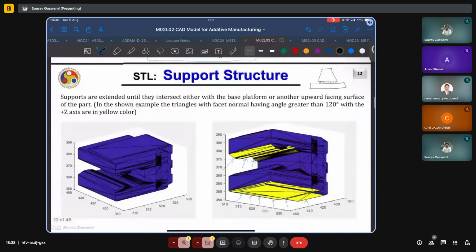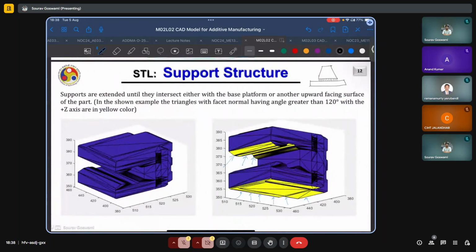In other processes such as DED, typically we may not use support structures at the bottom, and the understanding is that we'll separate it directly from the substrate plate and may have some allowance for it in the design itself.